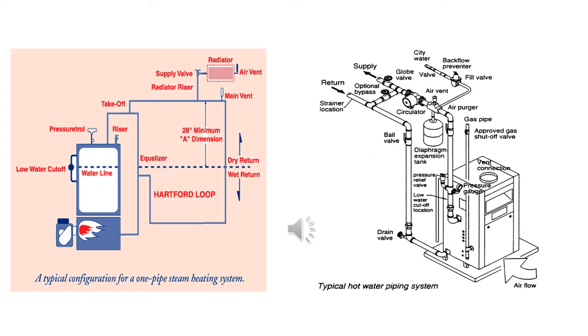There are three types of boilers that are used to produce and deliver heat to a conditioned space. There are forced hot water boilers, steam boilers, and boilers that can be configured as either a steam or forced hot water boiler. Boilers can be constructed of cast iron or steel. All of the boilers have similar features. Just as a furnace, they have a combustion chamber, heat producer, flame monitor, a heat exchanger, a method to protect the equipment from too high of a temperature, and a method of disposing of the combustion gases.